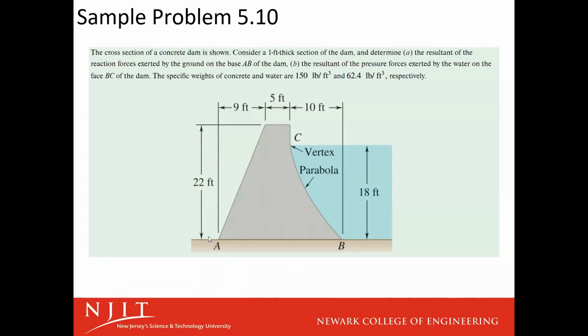There's also going to be a rotational force because of that concrete fixture. Each area of this is going to have some weight distribution, right? This is all concrete, it's all going to have a weight pulling down on it. We can use the density to figure out what that weight is pulling down on each element.